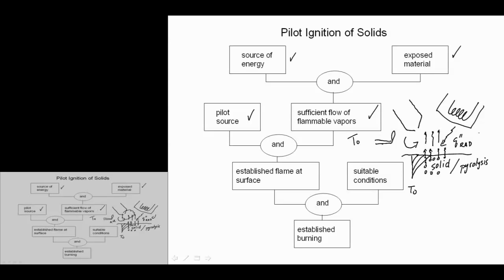So as we discussed with liquid problems, the mole fraction at the igniter still has to sit in a flammable range, and it's of course more complex with the decomposition products from a solid. It's not simple and clean. It's not typically one type of flammable vapor. It's a mixture of flammable vapors. And some of those rules that we talked about in terms of what is the lower flammability limit of a mixture would apply to the analysis here.